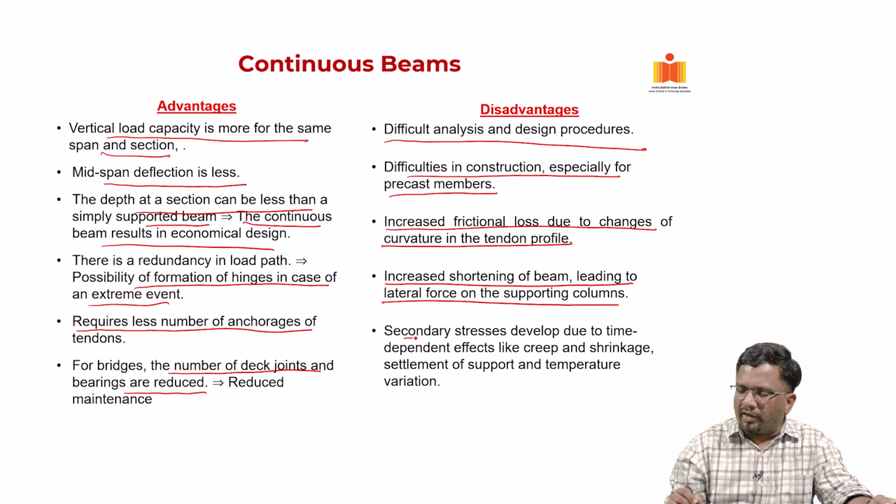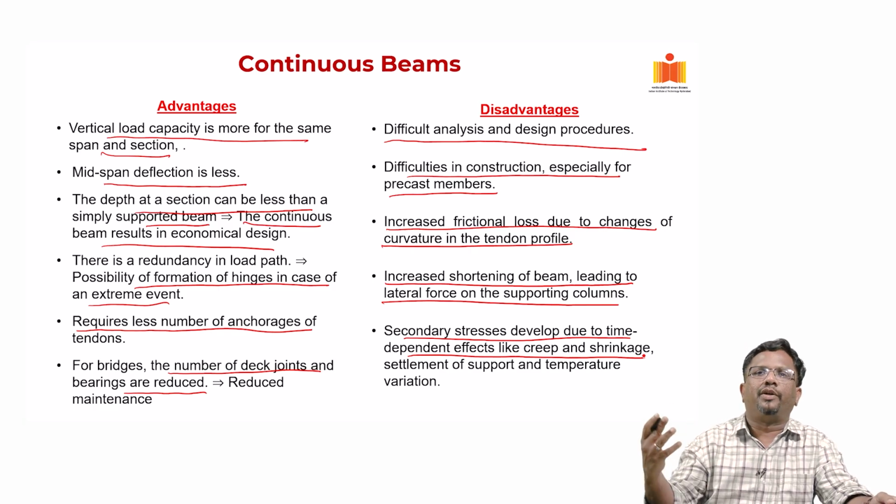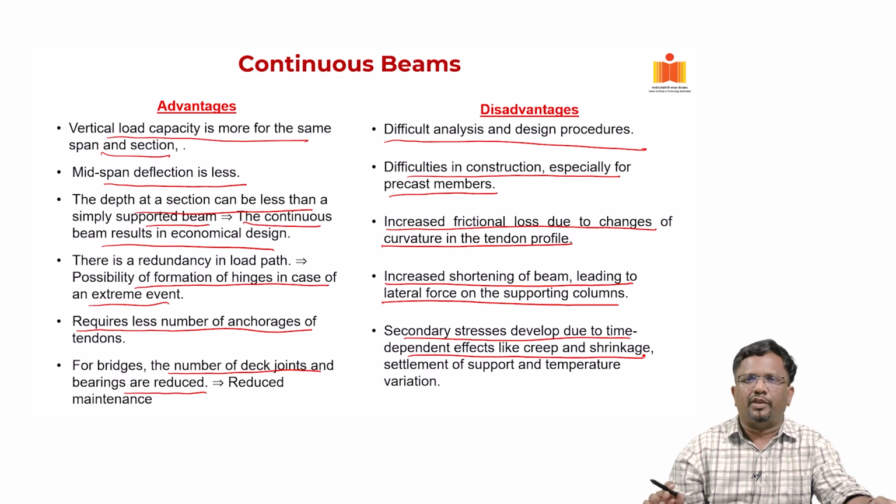Now, secondary stresses also develop due to time-dependent effects like creep and shrinkage. First of all, accurately calculating the effects of creep and shrinkage itself is not possible, and then there is settlement of supports, depending upon the support condition that you have. Again, it is a highly nonlinear process. It depends upon site conditions and it varies with time.